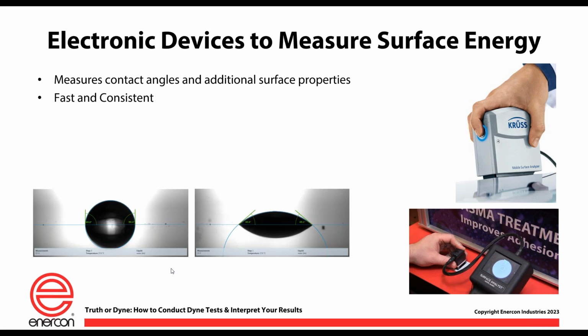And that will give you a contact angle value. Of course, the lower the contact angle value, the more the droplets spread, and in theory, the better it should be for an ongoing process. It is very accurate, and it is used as another measurement tool. I will say this to you guys: you want to use these two measurement methods discretely. If you're going to do dyne testing, that's one column. If you're going to do contact angle testing, that's another column. And those two columns don't really have a connection with one another.